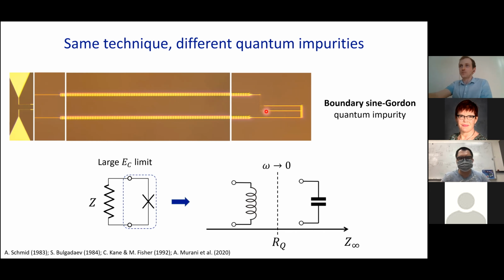and it's achieved by making the junctions smaller. This model is interesting because it also describes what is called a dissipative phase transition. The small junction sees this Josephson transmission line basically as a resistor connected to it. There is a prediction that the behavior of this junction at the lowest frequencies is either superconducting or insulating, depending on the value of Z. If Z is larger than RQ, then the junction is an insulator, and in our circuit language, it behaves like a capacitor.